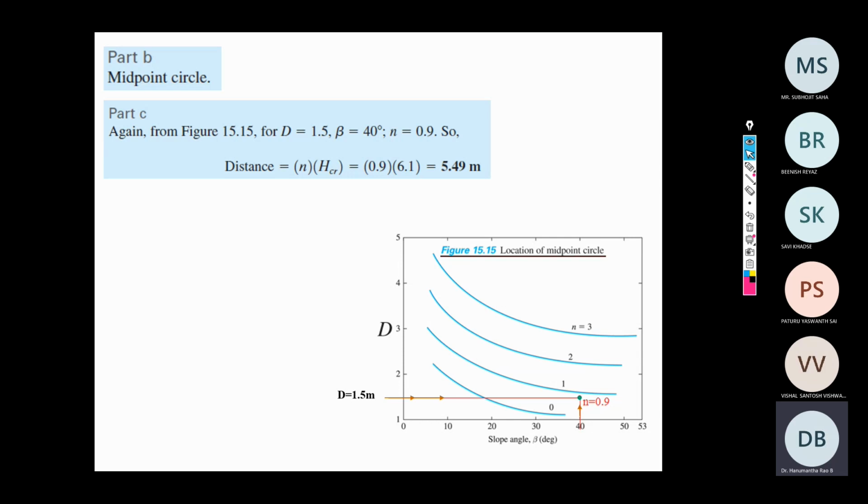Okay, so there is another logic also. See, for example, in the previous sum, the hard surface directly lies at the toe level. But in this case, the hard rock strata exists at more than 9 meter. So then you can presume that it could definitely be the slope failure. The chances for the toe failure are a little less. Okay, so that's how you need to understand or analyze the slope.